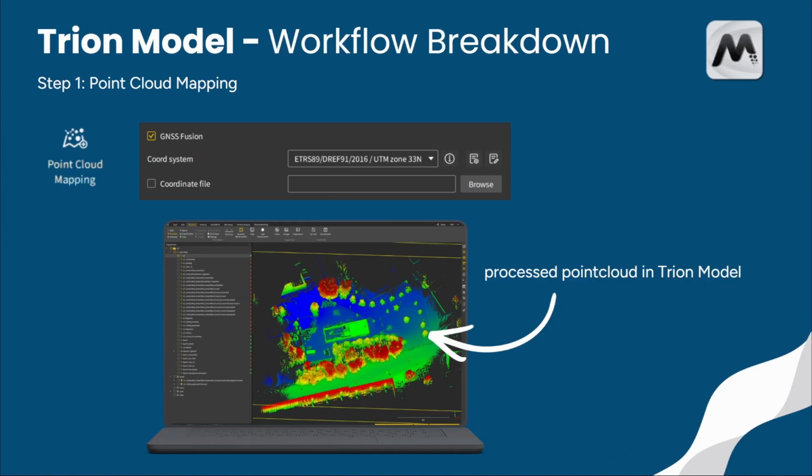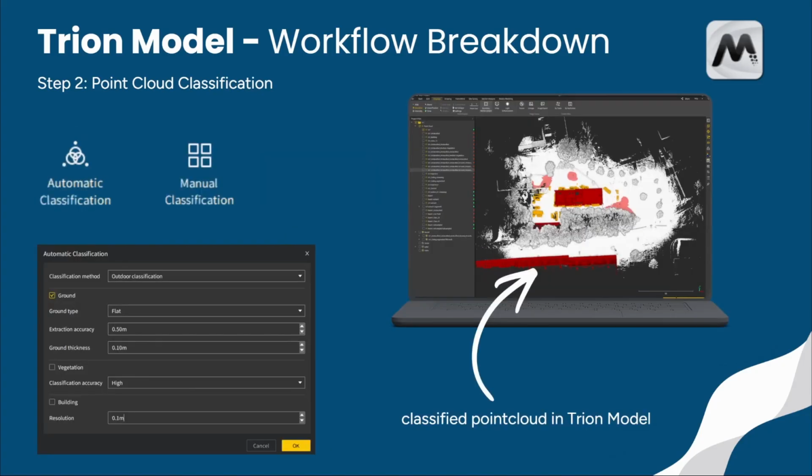The first step is point cloud mapping, which we use to process the captured data in Trion model. To georeference the dataset in the desired coordinate system, we use the GNSS fusion function. This allows us to accurately position the captured data and work with a georeferenced point cloud right from the beginning. Once that is done, we move on to automatic classification in order to extract the ground points.